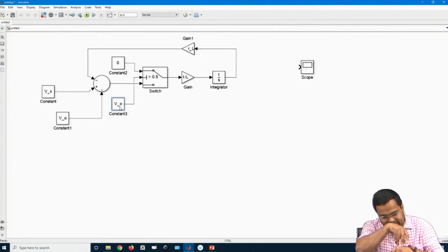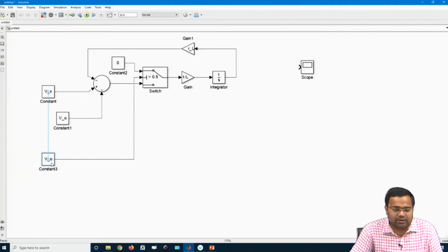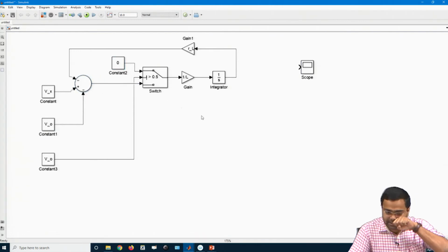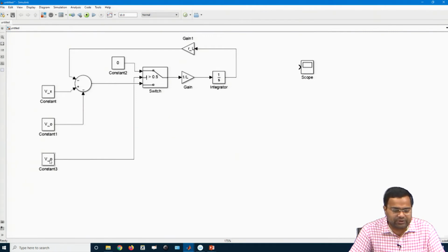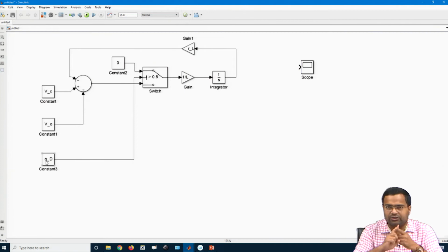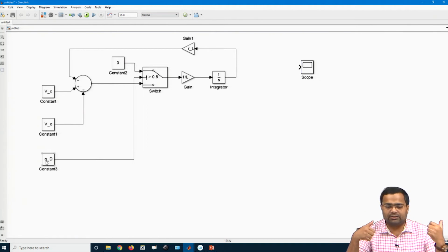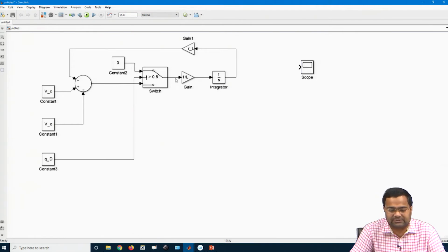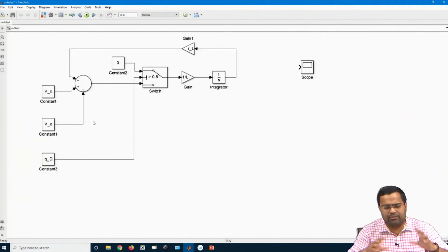So, in this what we need? This particular block has different input requirements, this is just a constant. So, if you take it for this inductor current dynamics realization, this QD, Q underscore D, is a logic signal which will be either 1 or 0. If it is 1, the VL will become 0. If it is 0, then VL will take its normal value, that means inductance voltage will be equal to Vx minus ILRL minus V0, that we have already realized.